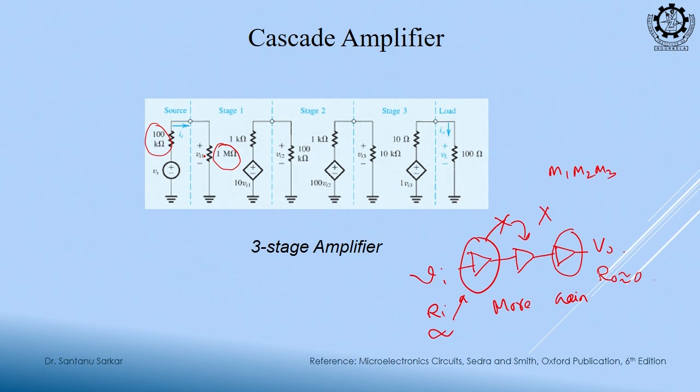So the first condition is more or less okay, that 100 k is much less than 1 meg. Otherwise, I will not get exactly Vs at the Vi, and some loss will be there; that is the loading effect. Clear? Suppose you want a voltage source with 0 resistance, but you get a poor voltage source with a high resistance, well, you have to work with that.